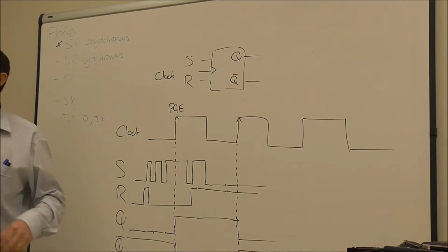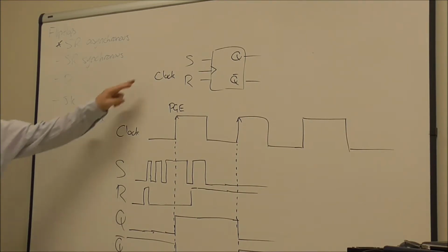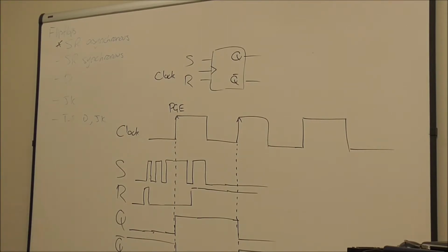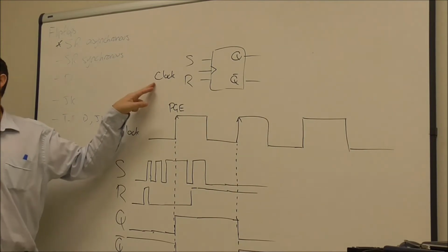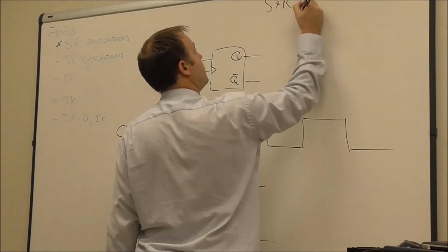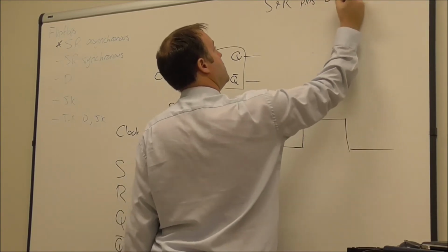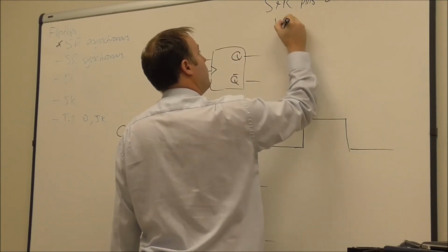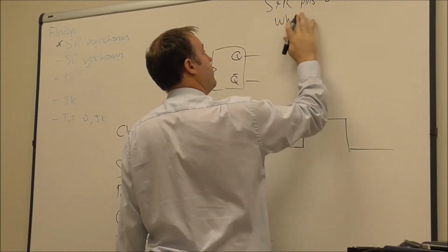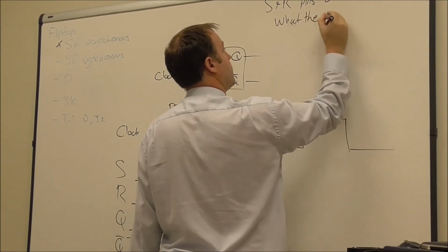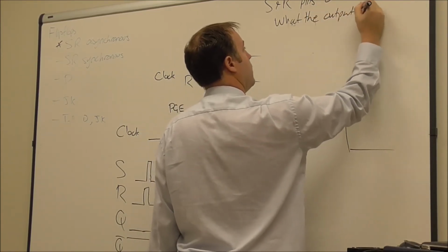Okay? They're controlled by S and R, so what they change to is determined by S and R, but the timing that they change is determined by the clock. Okay? So we could say that the S and R pins determine what the output becomes.